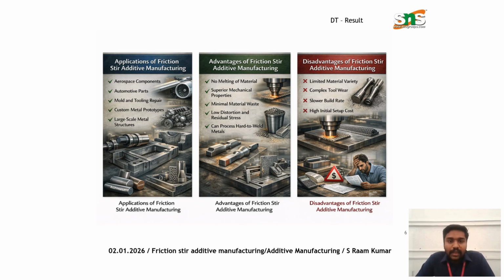Then the advantages will be no melting of material. The metal melting stage is not carried out here. Then the second will be superior mechanical property. Compared to traditional manufacturing, friction additive manufacturing based products have superior mechanical properties. And the third is the main thing, minimal material wastage.